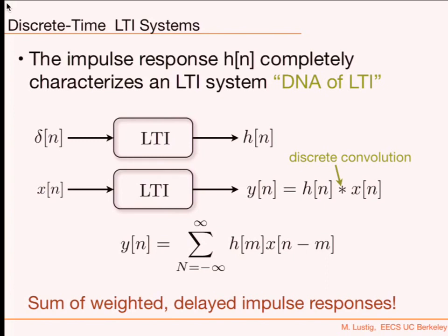Now, put any input whatsoever. What's the output? I don't need to know the system. Give me an input, no problem. I'll take the input, I'll convolve it with the impulse response, and I'll give you the output. I don't even need to measure what the output is. I'm going to tell you what it is. Extremely, extremely powerful.